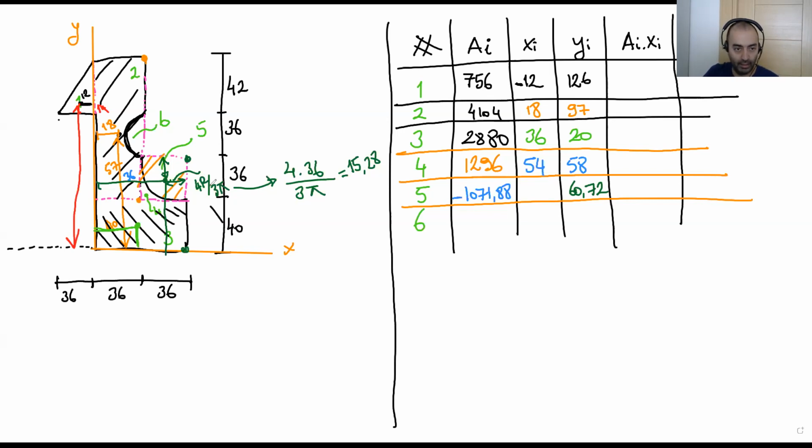I've just calculated this 4r over 3π here, and it's the same for this point, so I've calculated the vertical one. If we do it in the horizontal direction, this total distance from here to here is 72 minus 15.28. Yes, this part is 56.72 here.